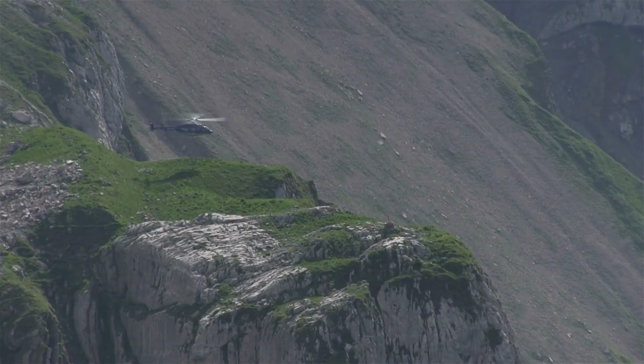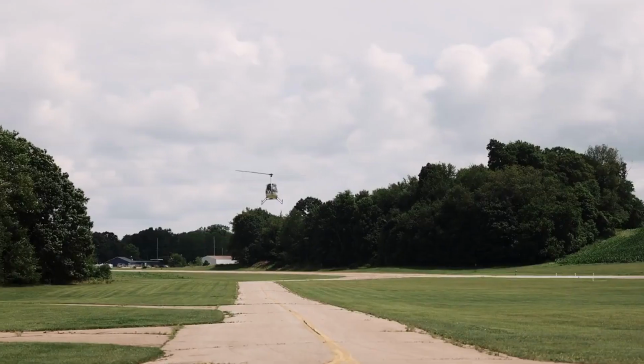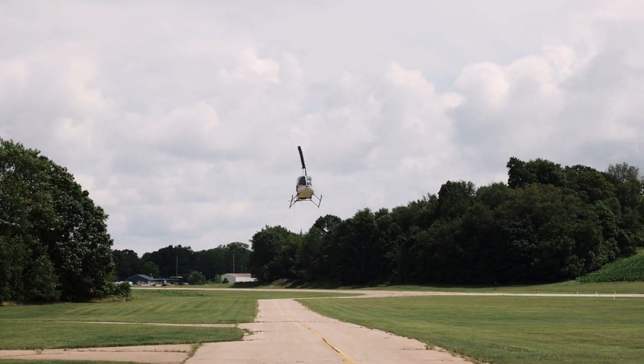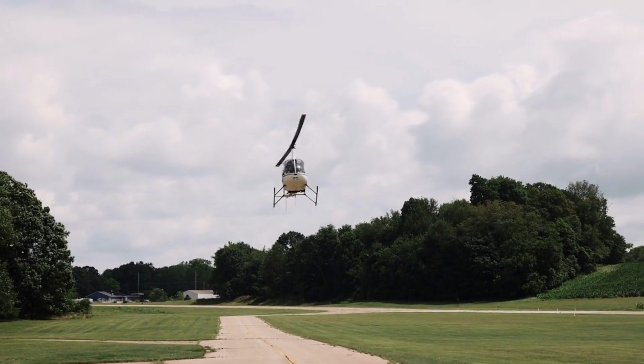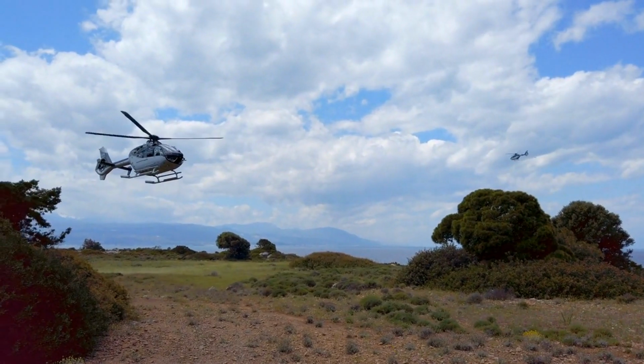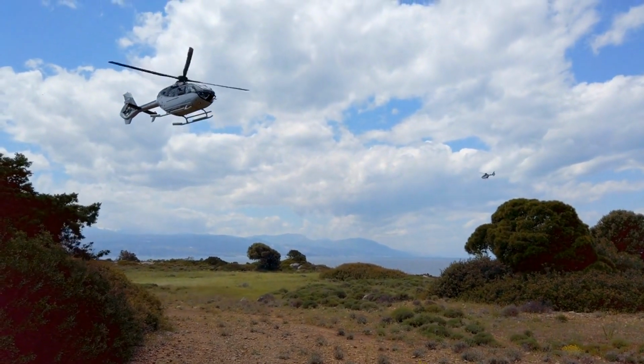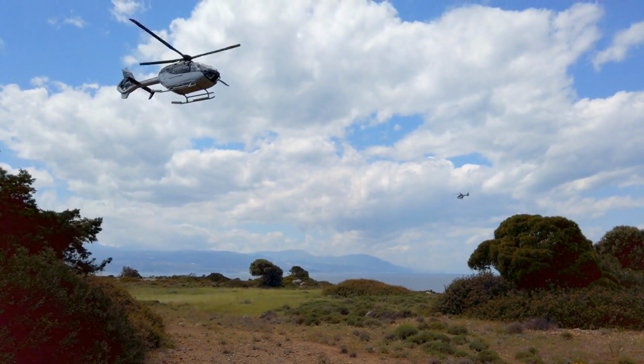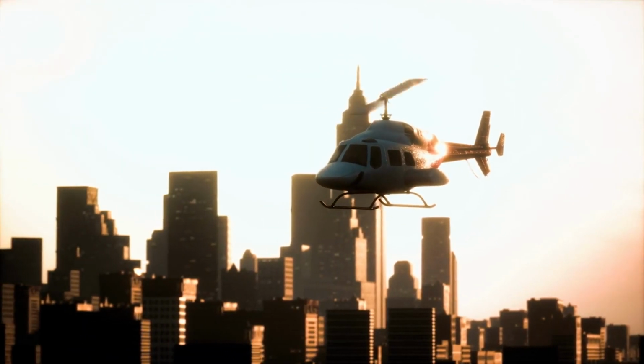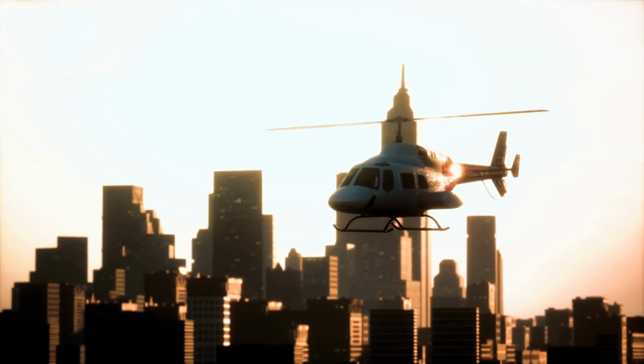Now, onto sideward hovering flight, a delicate movement when forward flight is impractical. Here, a constant ground speed, altitude, and heading are maintained with precision. Before embarking on this aerial ballet, the pilot ensures the area is clear, paying particular attention to tail rotor clearance. Two inline reference points guide the dance in the direction of sideward hovering flight.